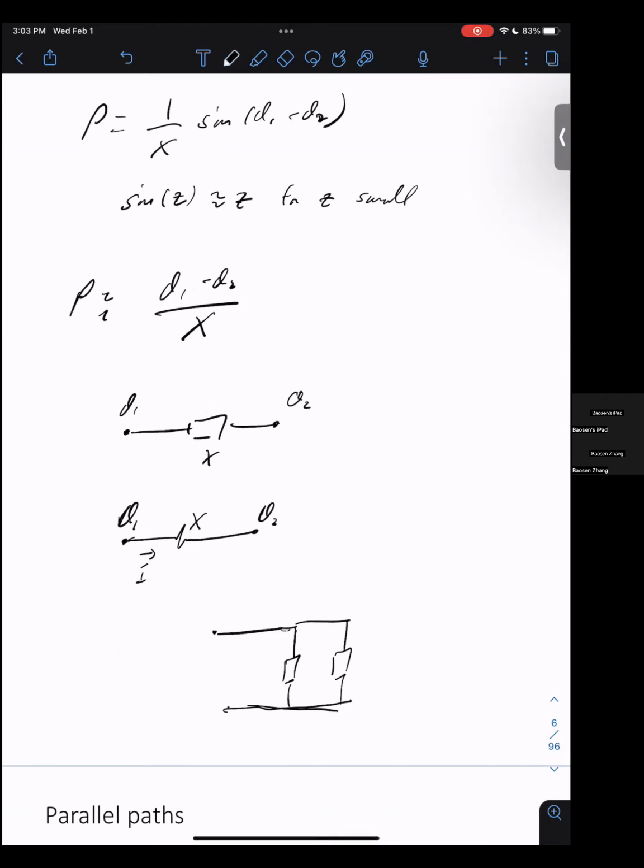Okay, you can ask, if I send over P here, how much is P1? How much is P2? It works exactly as if you have a current and two resistors that divide, right? So the division is exactly the same. From now on, pretend power is current, reactance is a resistor, and do current division.